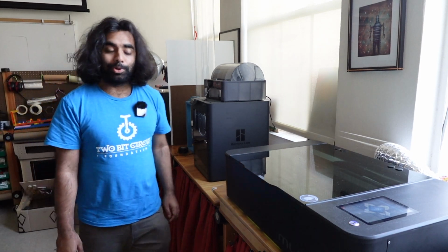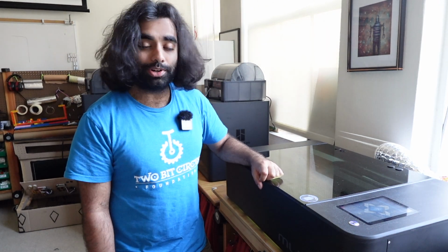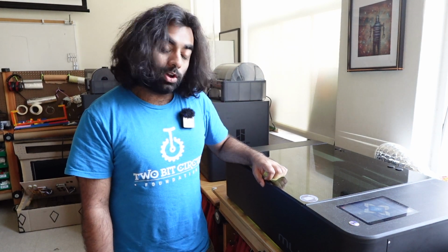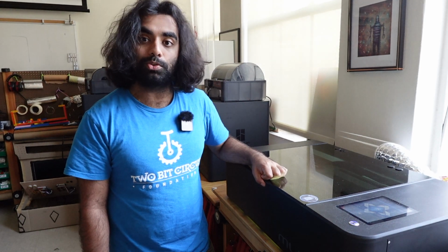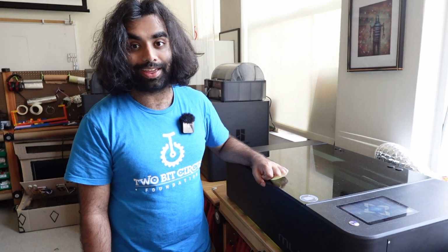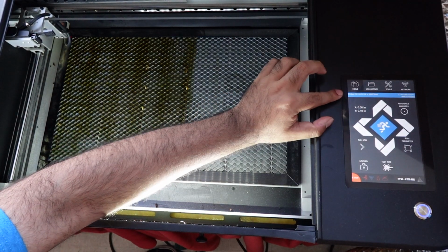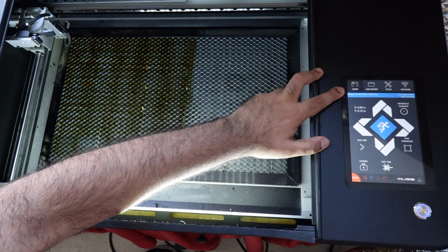In order to get started with your laser, you first have to access your design software. To do so, you're going to want to locate the IP address which is associated with your laser. In order for this process to work, the computer that you connect to your laser with must also be on the same Wi-Fi that your laser is connected to via Ethernet. To locate your IP address, you can find it in the top left section of the blue ribbon at the top of your touchscreen, underneath the main settings.